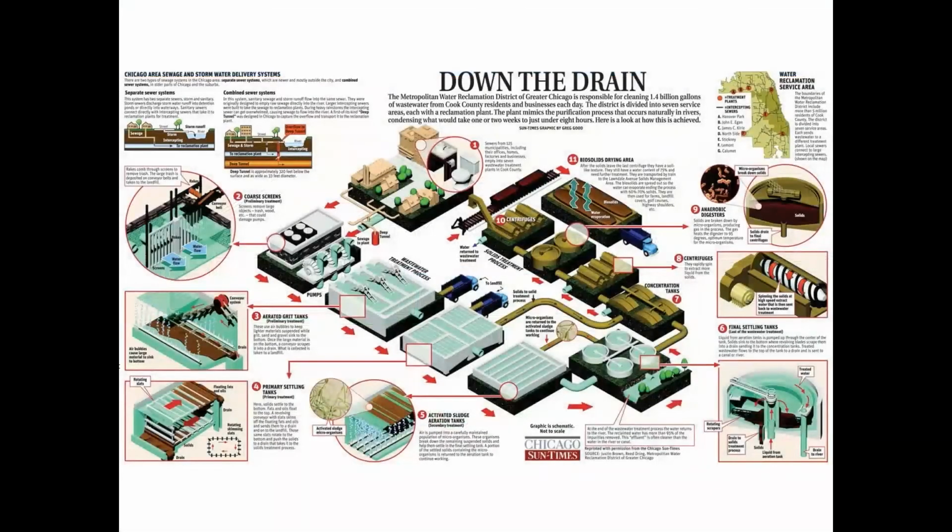This is a schematic of a wastewater treatment process that is typical at our plants. There's kind of a lot going on here, but in a nutshell, the wastewater enters the facility and is screened for large debris so that anything bigger than about 3 inches will be caught up in bar screens. It is then pumped from there for the first and only time to the grit tanks to remove larger particles like sand and gravel, which can be harmful to the facility's infrastructure.